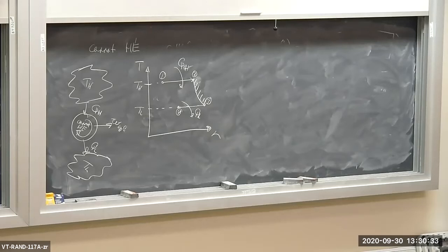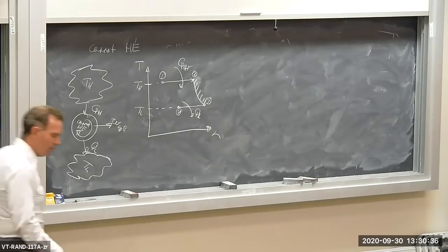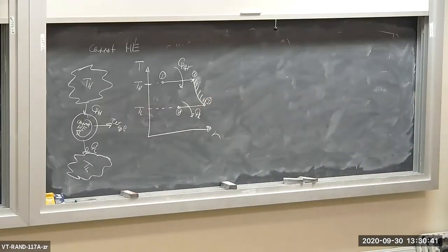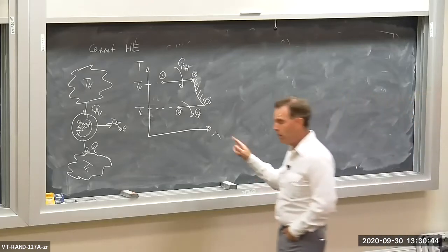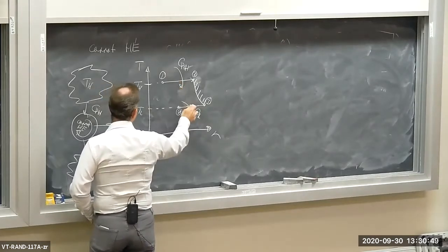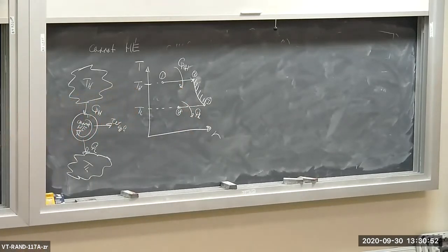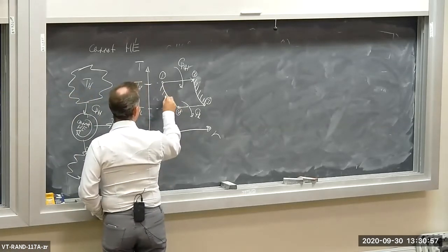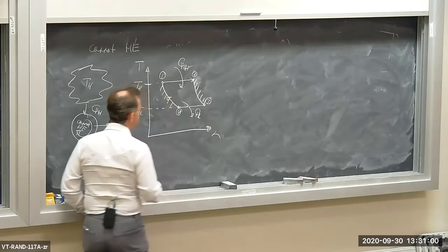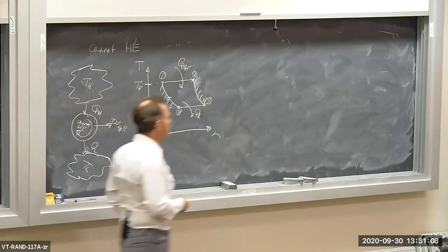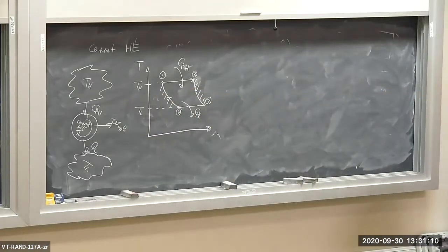Again, the system, the working fluid inside the Carnot heat engine, our piston cylinder device, operates frictionlessly, slowly, so there's no unrestrained expansion and there's no heat transfer across any finite temperature differences because all the heat transfers occur at either the high or the low temperature reservoir temperatures. And then we complete the cycle by having adiabatic compression back up to state 1. So that's the Carnot cycle for a heat engine. This is reversible because it contains no irreversibility, so let's reverse it.